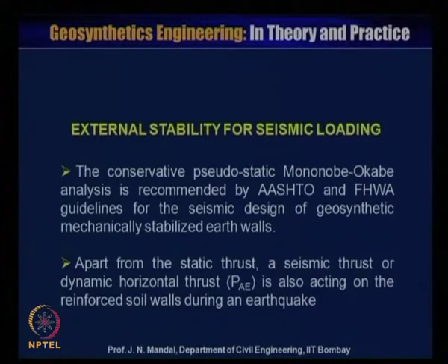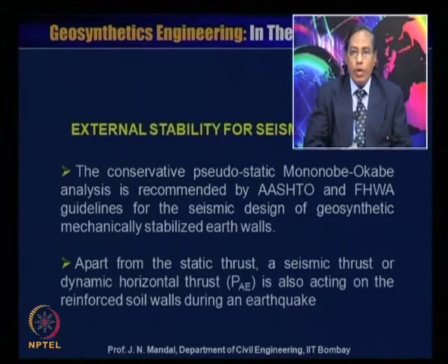Now external stability for seismic loading. The conservative pseudostatic Mononobe-Okabe analysis is recommended by AASHTO and FHWA guidelines for the seismic design of geosynthetic mechanically stabilized earth walls.